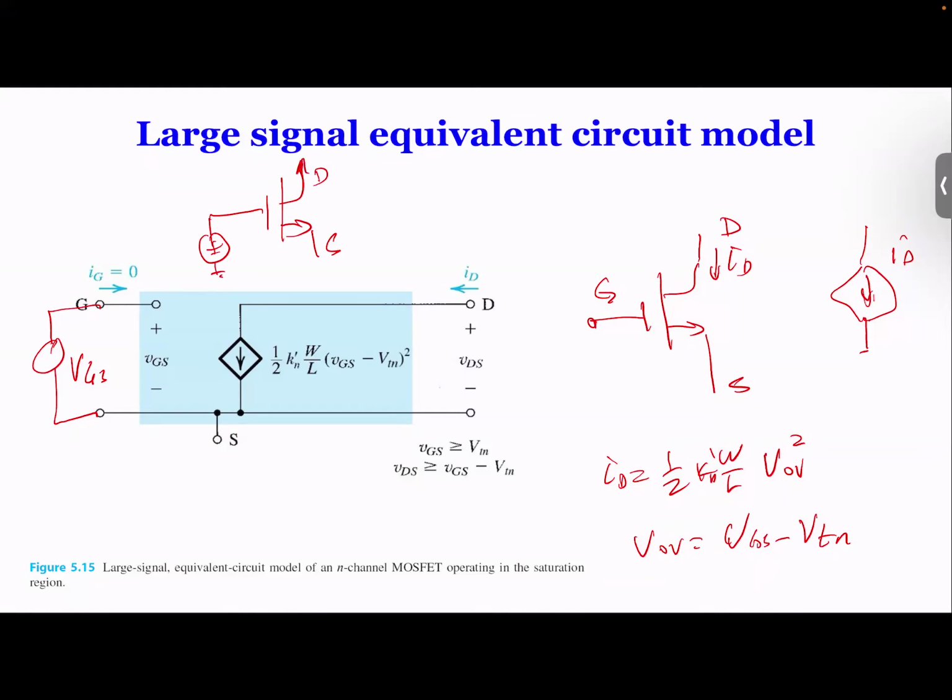If we have a voltage source and we have ground over here, we have ID. So if you look at this equivalence, the actual MOSFET circuit, you have VG connected to the gate. Because the gate is insulated, there's no current. It's like an open circuit. So that's why we have VGS floating, because it connects to your gate, and the gate is floating.